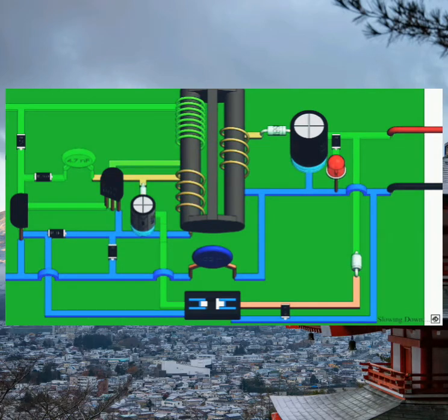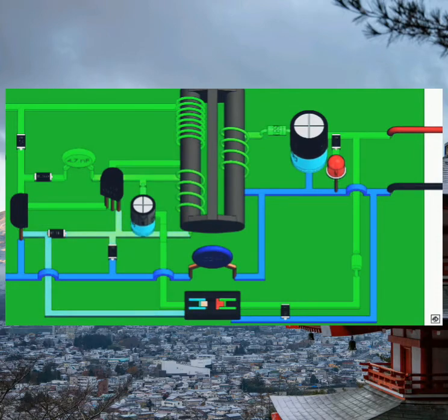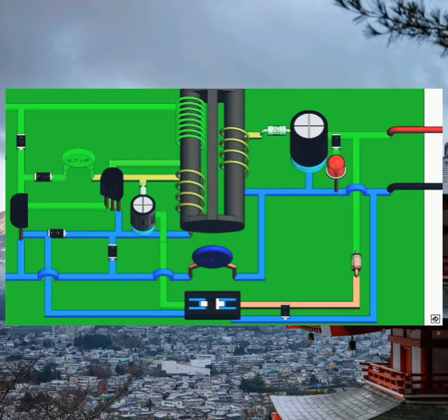As we reach 4.2 volts, the Zener diode turns on, allowing current to flow to the optocoupler. It also drops the voltage by 4.2 volts, hence the LED of the optocoupler doesn't turn on. The LED requires 0.8 volt to turn on. When the voltage reaches more than 5 volts, this turns on the LED of the optocoupler. The light of the LED turns on the phototransistor of the optocoupler, allowing the current to flow to the transistor T2. This turns on the transistor T2, shunting the first and stopping the flow of current in the primary winding. Also, the voltage in the secondary side of the transformer drops below 5 volts, turning off the Zener diode and optocoupler, and the circuit continues to run normally.